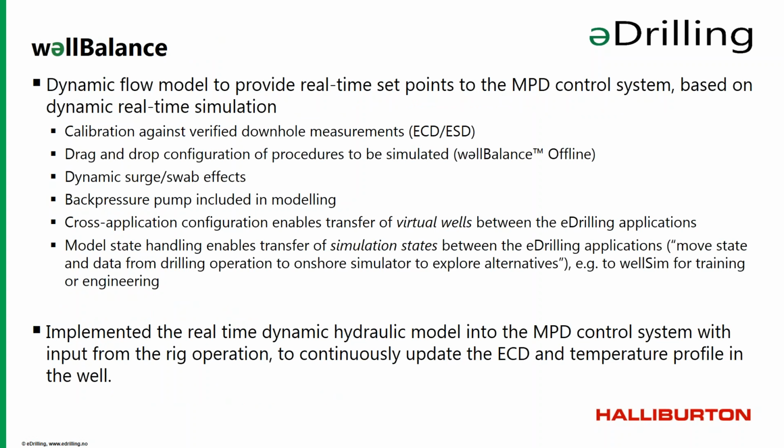Okay, and then when we talk about WellBalance, we have this dynamic flow model that is used to provide the real-time set points to the MPD control system based on a dynamic real-time simulation. This model is calibrated against verified downhole measurements. You can do drag and drop configurations of procedures to be simulated. The model supports dynamic surge and swab effects. The back pressure pump is modeled as well. And we also have the cross-application configuration that enables the transfer from one application to another.